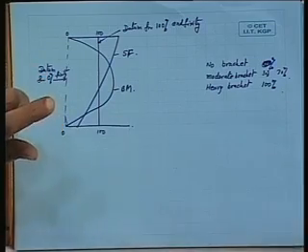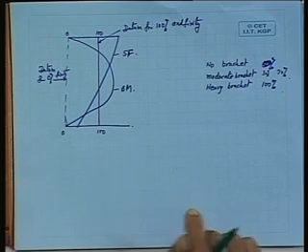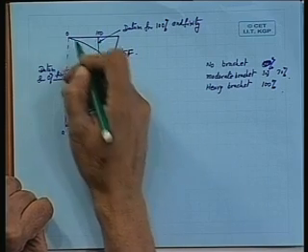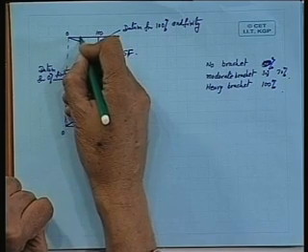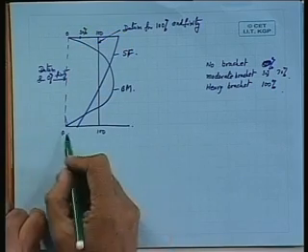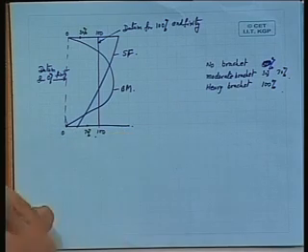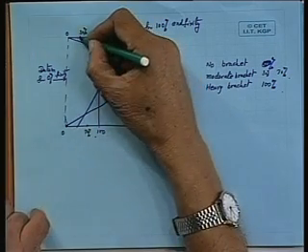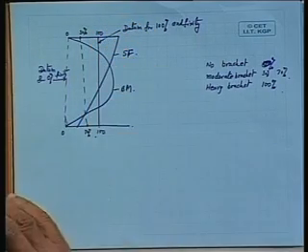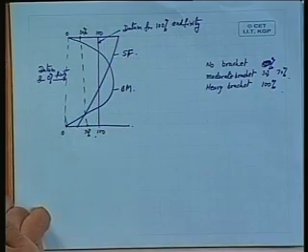And maybe my bracket connections are such that I get 30% fixity at the top and 70% fixity at the bottom. So, this is my 0, this is my 100. If I say 30% in the top, so I try to measure 30% here. This is 0, this is 100, 70% at the bottom, this is 70%. And when I join these two points, this gives me the datum for the condition which I have chosen.